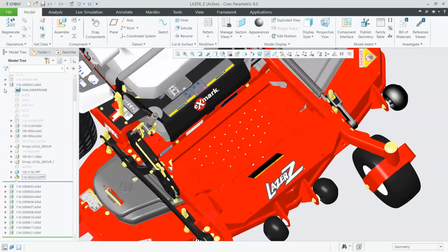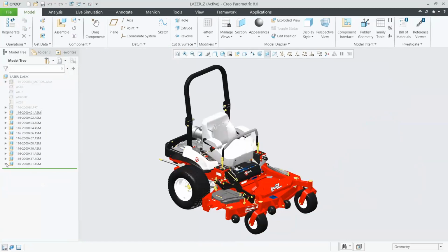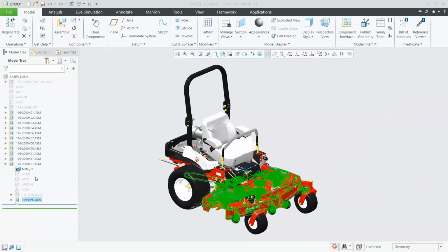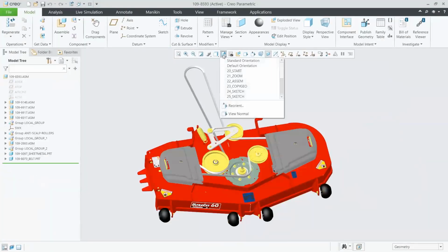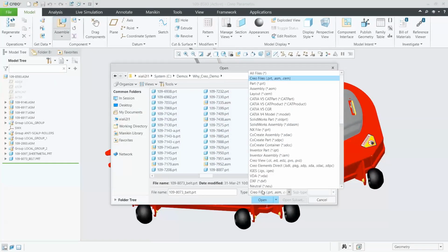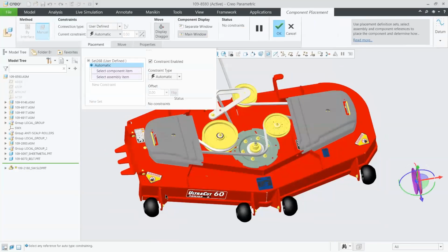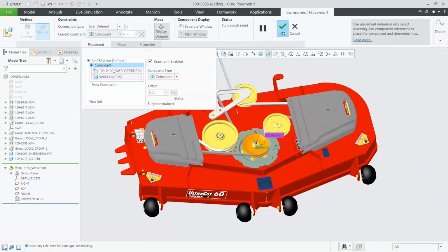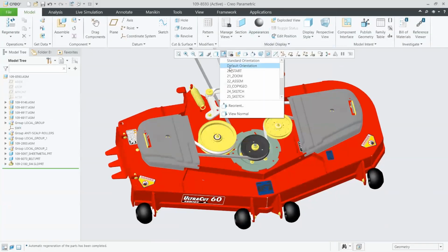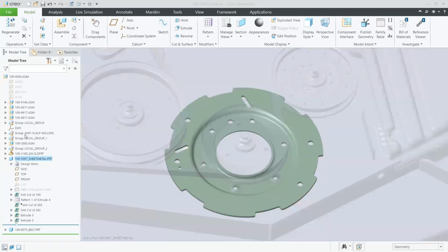And now moving on from this point, there's another file that we've been provided, possibly from a partner or supplier that we need to pull in and use here in our design. So here we'll be working within one of our sub-assemblies. And in this case, it's another SolidWorks part. So we'll just go ahead and take that and assemble it in similar to how we did with the first part. Go ahead and bring that into the context of our assembly here. Let's tie it in with the default coordinate system in that case. And you can even drag it back in the feature history if you'd like to, right? We can design our other features based off of this if we'd like to as well.